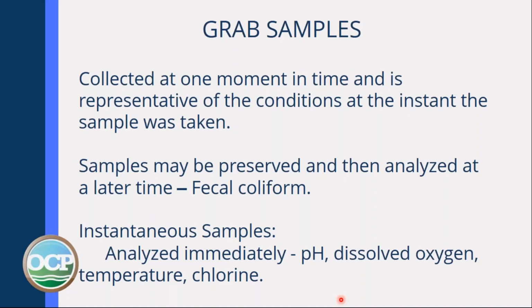But a lot of grab samples you will take as instantaneous samples, and these are the ones that you're going to analyze straight away, usually with a specific meter, such as a pH meter, dissolved oxygen, recording the temperature, and depending on where you're taking the samples, the chlorine levels. So you're not discharging chlorine into the receiving waters of the Commonwealth.